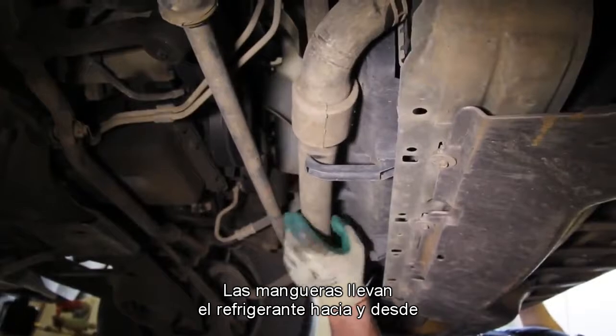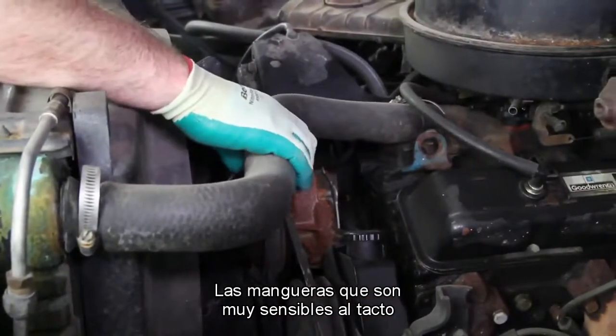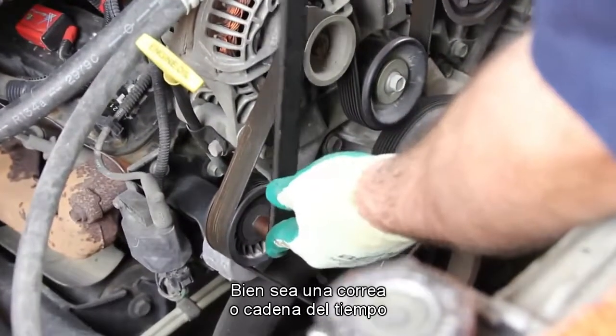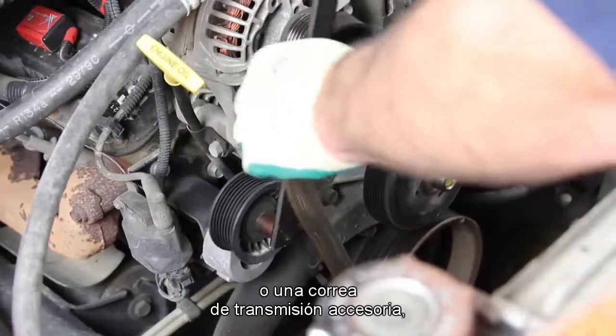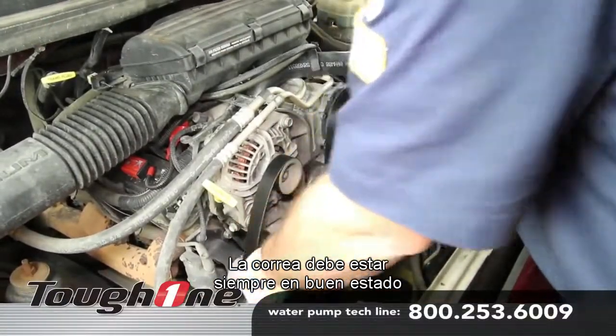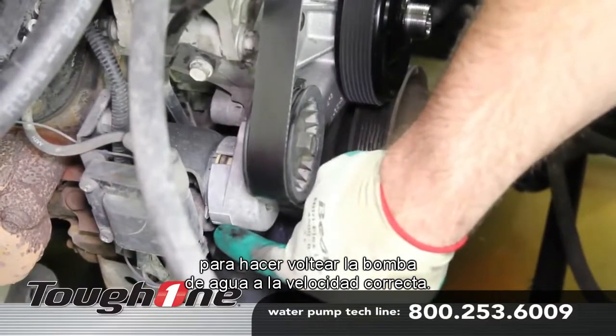Hoses carry coolant to and from the radiator and heater core assembly. Hoses that are spongy to the touch or that have cracks present should always be replaced. Whether it is a timing belt or chain, or an accessory drive belt, belts are often the driving link that turns the water pump. The belt must always be in good condition and have the proper amount of tension to turn the water pump at the correct speed.